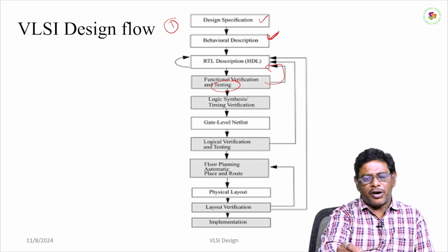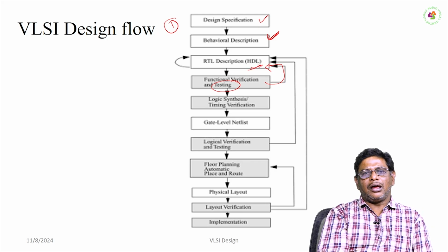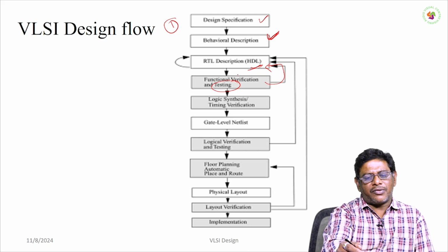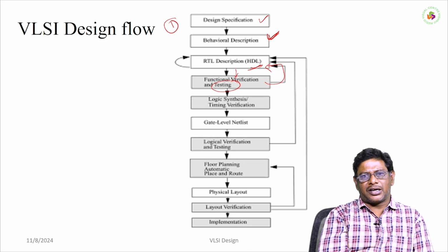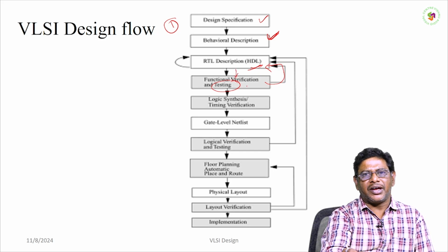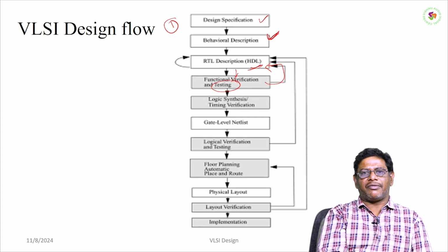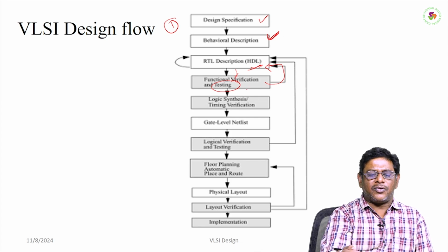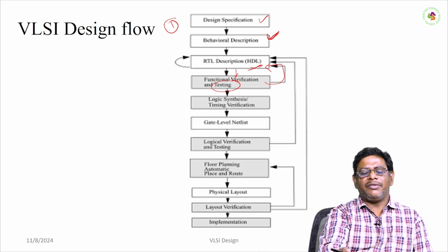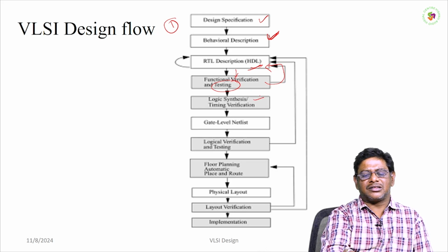If not, we will be modifying some of the designs in the RTL design. Then again we are going for verification of it. Then we are going for testing. Once it is proven in all the results, then we are moving on to logic synthesis and timing verification. The next step of functional verification and testing is logic synthesis.